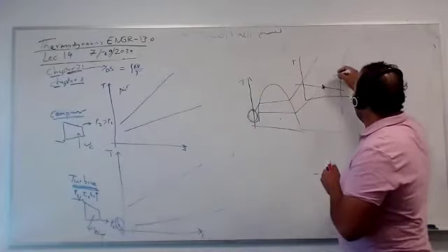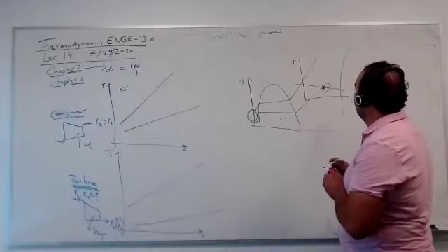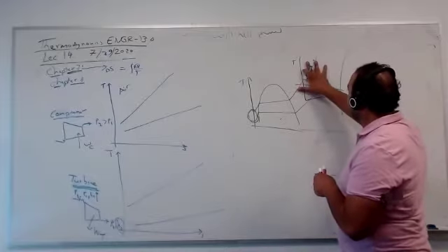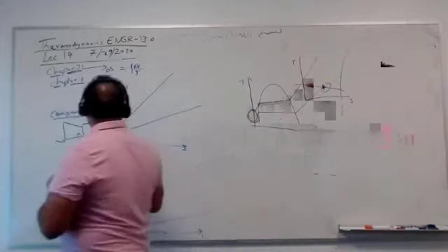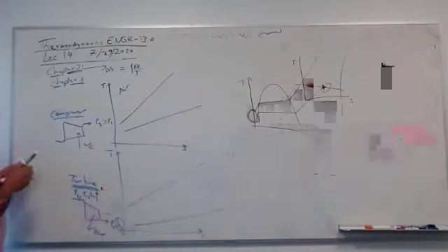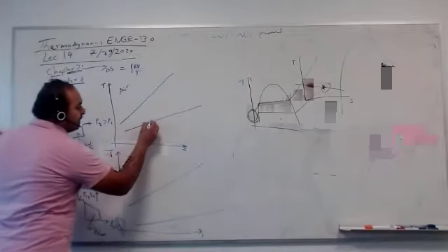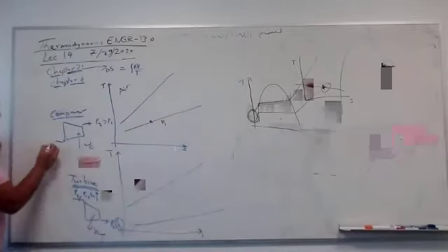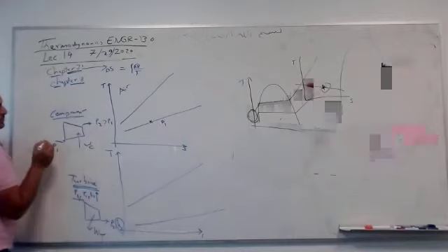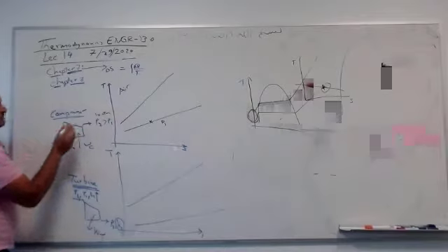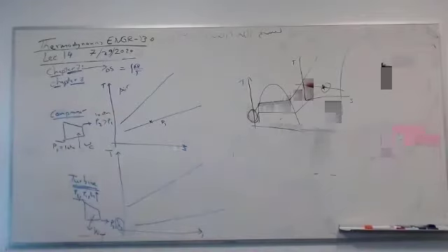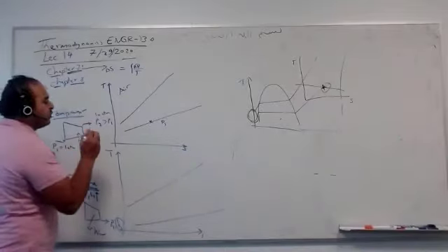So we have air and liquid water at the same time. Now, the air is vapor or gas, the water is liquid. So here, this is the air. Let's say I'm here. This is pressure 1. I want to compress this flow to a higher pressure. Let's say from 1 atmosphere to 10 atmospheres, 5 atmospheres, 8 atmospheres, a higher pressure. If I am adiabatic, no friction, no losses, reversible, I am supposed to move isentropically.